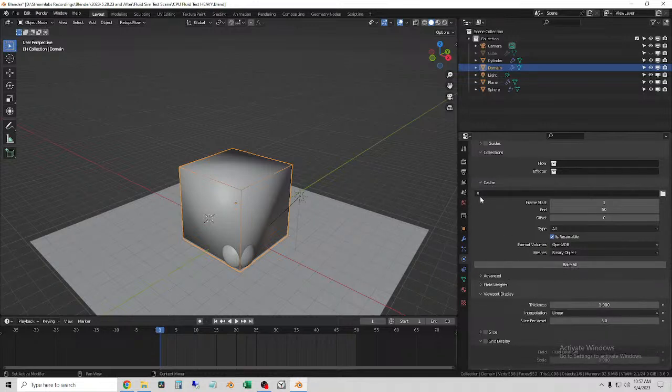It's going to default to the // which is the destination where your file is. So if you ever see that, the directory is just pointed to the same place your file saved. So you'll have to save this on your system somewhere, and then it'll give it a place to store the cache, and then you hit bake. It'll start to run it. When it gets done, record the time. It'll pop up down here on Blender, or you can record it manually, just with a timer.